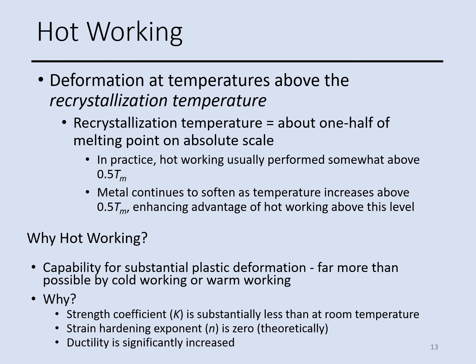The temperature you can approximately calculate by this equation, 0.5 times melting point. Again, if you have a steel with a melting point of 1500, multiply 0.5 by that 1500, and it gives you 750. This is about the temperature you need to work.